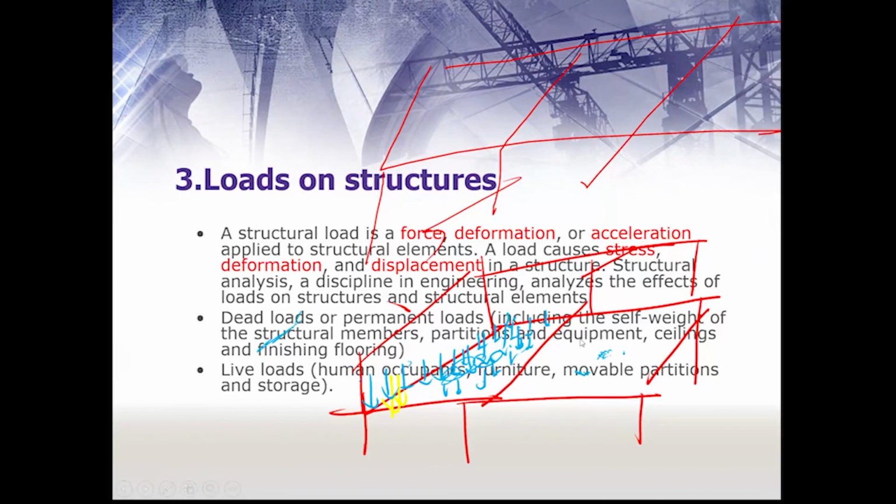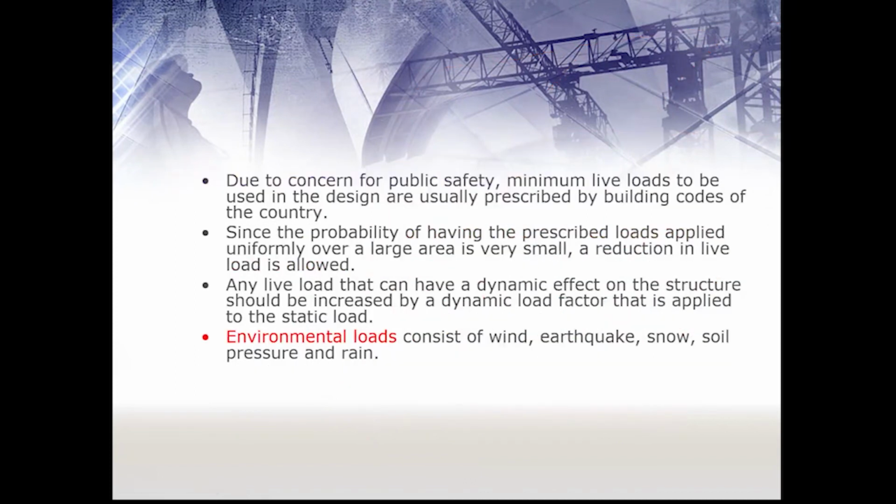That's why the live load is the load that can be applied for a certain time and then it can be removed. Due to the concern for public safety, minimum live loads to be used in the design are usually prescribed in the building code of the country. They will tell you that for each type of structure there is a specific live load to apply.